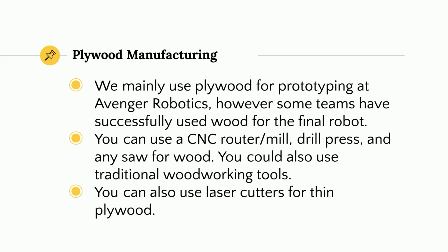You can also use a CNC router / mill, drill press, any saw for wood. You can also use traditional woodworking tools. Essentially, any tool in your shop besides a plasma cutter or a welding machine can be used with plywood. You can also use laser cutters for plywood. However, I would put the caveat that some of the glue in plywood that keeps the sheets of wood together can cause problems with the laser cutter. I would just say stick with thinner pieces of plywood for laser cutting.